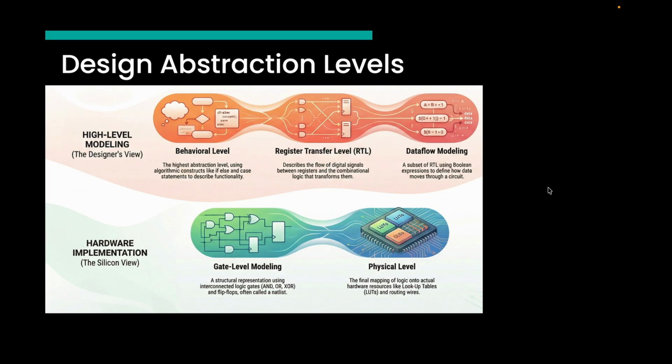The physical implementation process involves technology mapping, where at this stage, it is about assigning the abstract logic gates to the specific physical hardware resources available on the FPGA, such as the lookup tables and specific registers. Placement involves determining the exact physical location for each logic block on the chip to optimize timing and space. And routing is about establishing the physical electrical pathways and wire connections between all the logic components using the FPGA programmable interconnects.